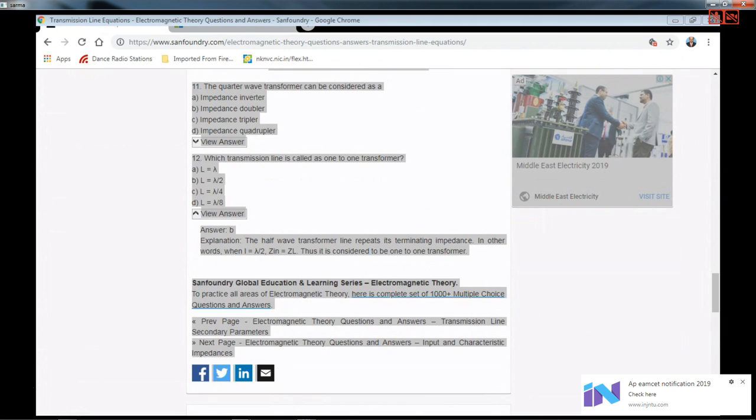So, to overcome these problems, people have come out with a different parameter, which is very simple, again dimensionless and measurable, and it is measurable at a number of locations, so that you can take an average of these values and reduce the measurement error. That's how a standing wave ratio has been introduced. The purpose is to see that we can measure this quantity at a number of locations simultaneously without much of a problem, and take an average value of this so that the measurement error is very, very minimal. Okay, this is what we know in all our measurements classes.